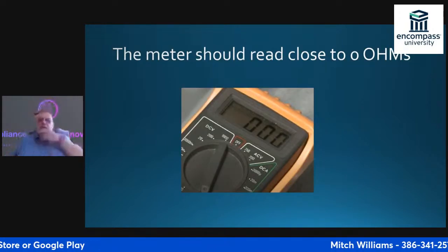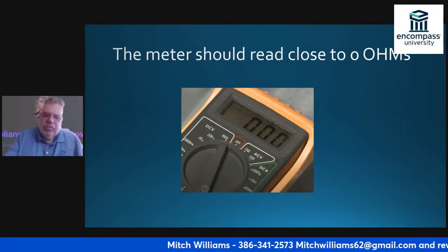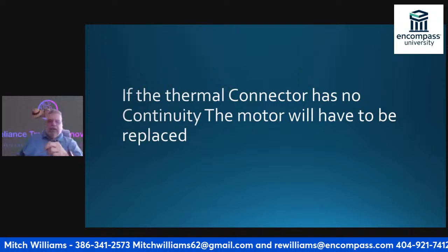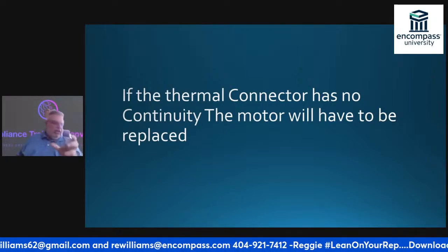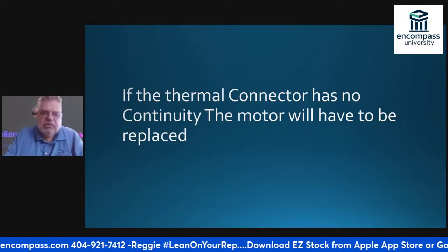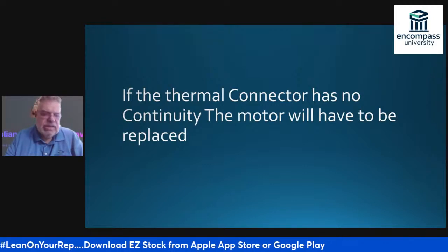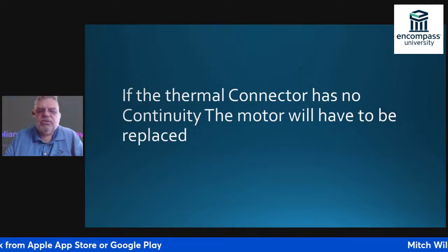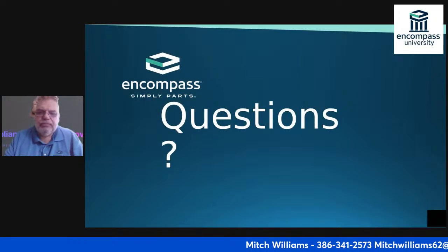The meter should read close to 0 ohms. If it has no continuity, it tells me that the thermal connector is not any good. And most of the time, you're going to have to change the motor. Most of these thermal connectors are no longer something you can replace.